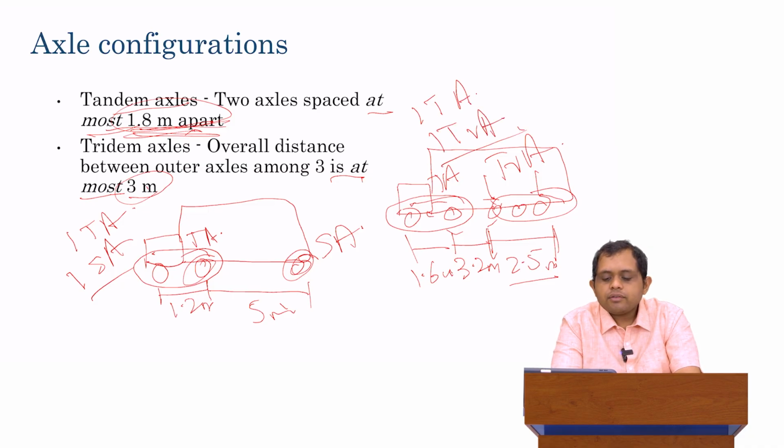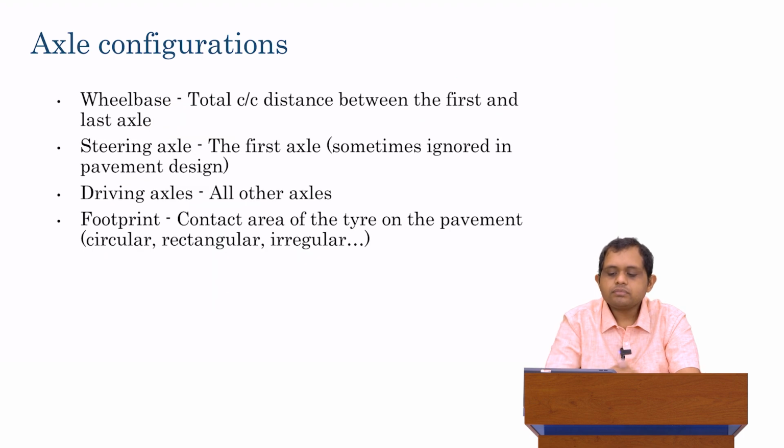So in this way, we can take our classification. If it's FHWA, class 4 to class 12. If it's IRC, then it's type 2, type 3, and their subclassifications. For each of them, we can classify the number of single axles, the number of tandem axles, and the number of tridem axles on each of them.